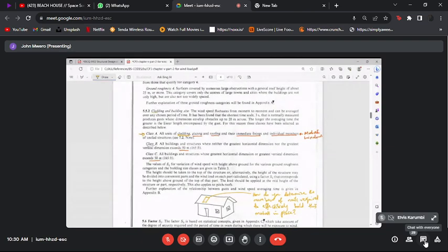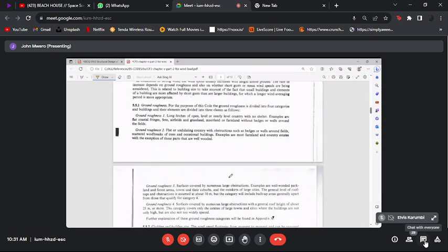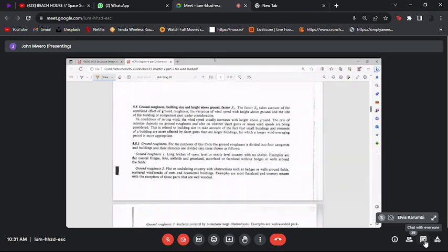Class A, you classify that as class A of the building size. And that will be eventually captured under the site-specific factor S2. The site-specific factor S2 deals with ground roughness, which we talked about in a previous session, and the building size, which we are talking about now, okay?